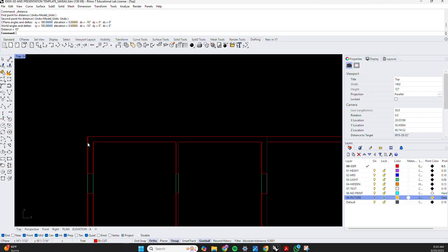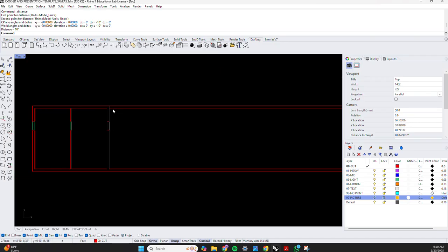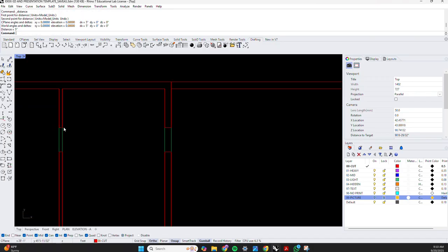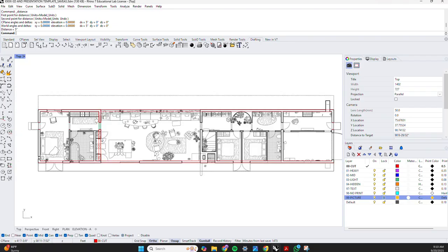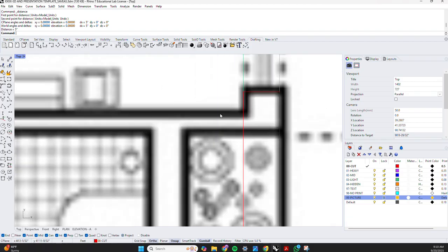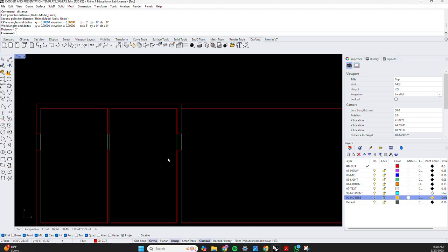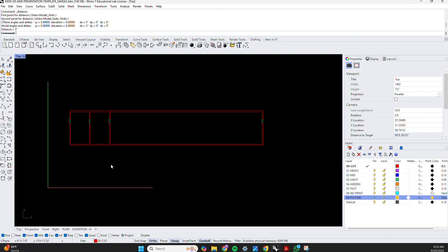Let's look at every exterior wall. 10 inches, 10 inches, 10 inches, 10 inches. Let's look at some interior, that interior division. 5 inches. You know, there's obviously more interior spaces. If we had one coming across, that also would have been 5 inches. And even if you were to have really zoomed in and got really close to the center of this line by doing a straight up trace the whole thing exercise, I think if we were zoomed out a lot, you probably couldn't tell the difference.